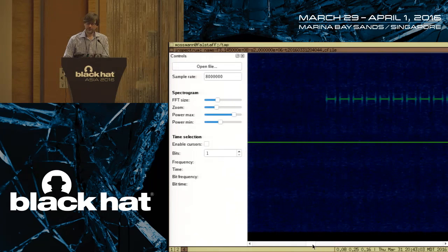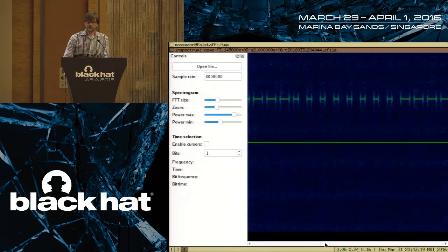individual pulses. They kind of look like an I-beam, or like a capital letter I turned on its side, because there's a little bit of frequency spreading when there's this abrupt on-off transition. This signal is turning on or off. But you'll notice if you look horizontally, if I scroll through here, do you see how everything is all lined up horizontally? They're all at the same frequency. Every single pulse is at the same frequency, which tells me this is not a frequency modulation.